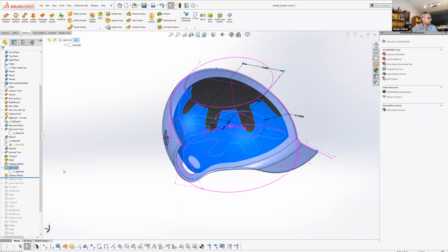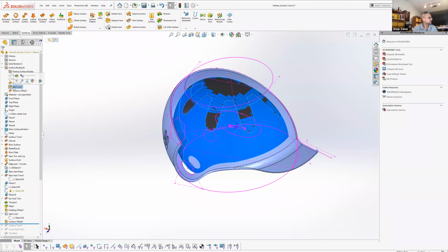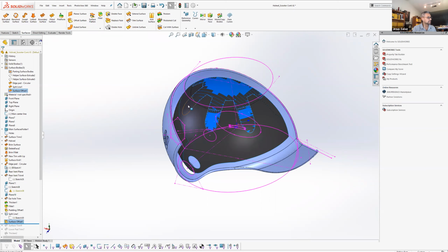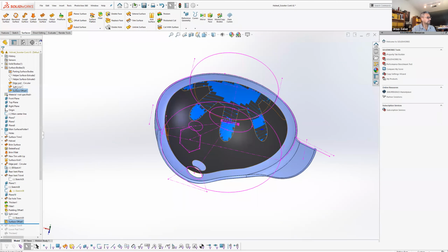And then I created another surface offset of just this face, basically to create a copy of it. So I have this surface up here. Actually, it wasn't the bottom part, it was the top split area. So I selected each one of these faces, all of these guys here, and did another offset because I wanted basically a copy of it.